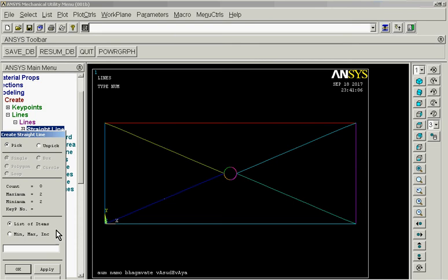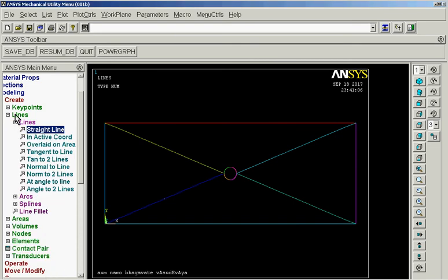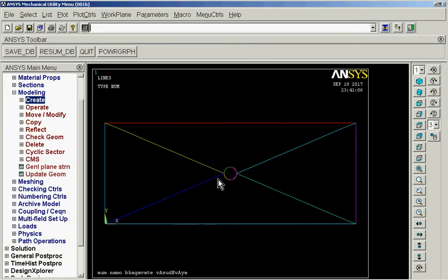Which of course is a pathetic mesh. It's not going to be good. I'm going to be going ahead and deleting this off because I have a triangle here. Obviously, since it's a triangle, it's not going to be able to completely sweep mesh, because you can't sweep from one place to another without having to lose the complete structured mesh. So I'm going to delete it off.